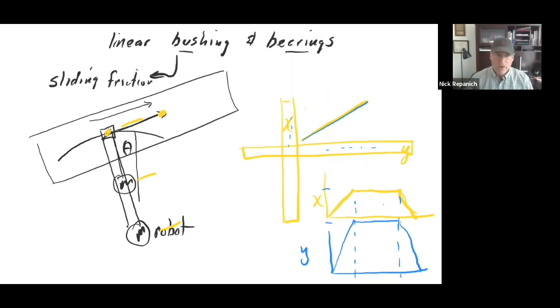So back to why do I need to teach linear bearings? There's a much smaller subset of people that are actually designing linear bearings into something. If you went out to a processing plant, like where I grew up, we had a walnut farm, and we had a huller and dryer. We had conveyors and augers and we were moving things around. I don't think there was a single linear bearing; everything that we moved was rotary bearings and then belts or chains and more rotary bearings. And they're fairly simple to keep the dirt out of because you can put a seal on it.